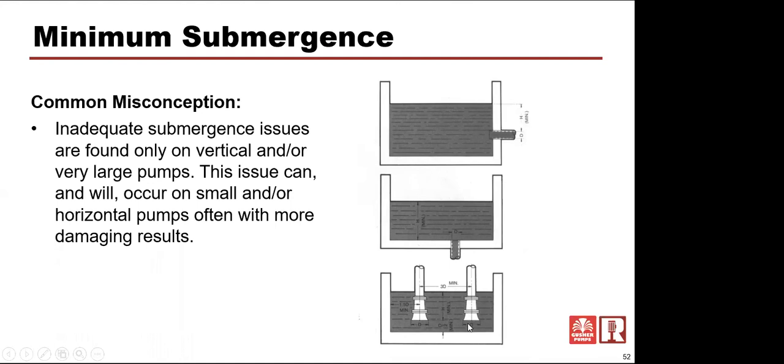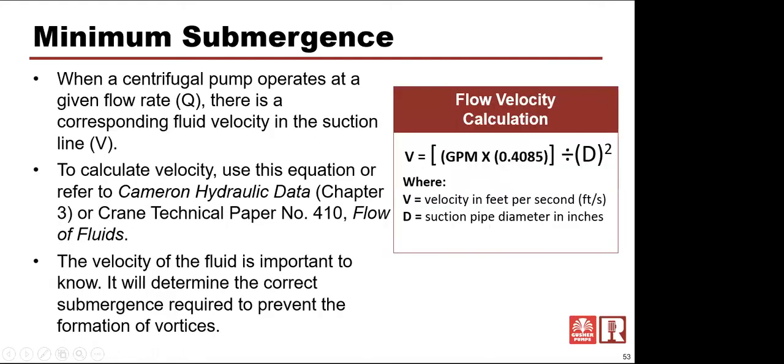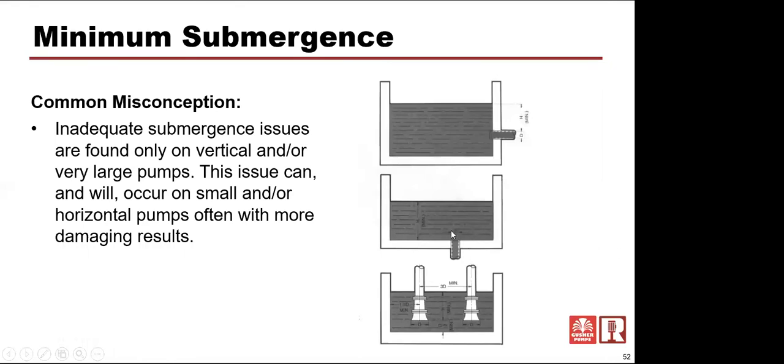And the other important thing when you have pumps like this, let's say even a horizontal where you may have two intakes coming off the bottom of a tank, is you want separation between those intakes, so that you're not creating a lot of swirling disturbance of water trying to come into this pipe, being affected by a pipe that's too close to it, by the turbulence around that.